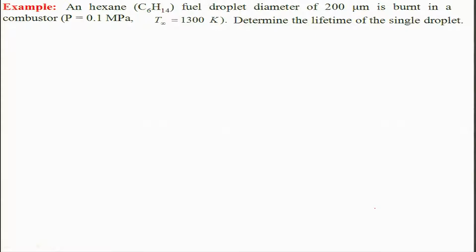And keep in mind, as I told earlier, it is very important to understand how one can do that, because although we have used quite a complex relationship for estimating the transfer number, that will not affect the droplet burning rate much. So also the droplet lifetime, and for that we need to look at the properties. So, let us look at an example to illustrate that point.